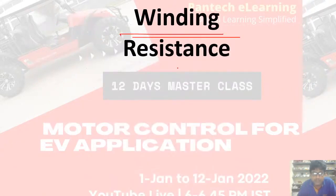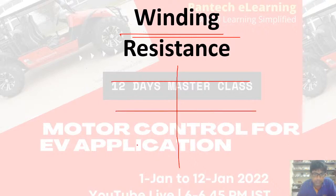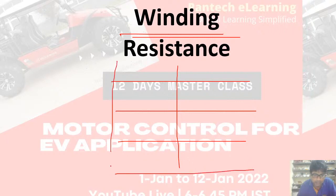Now the winding resistance. For winding resistance, simply you have to follow the data sheet, because no standard will tell about the acceptance criteria of that, because this depends on your electrical design.